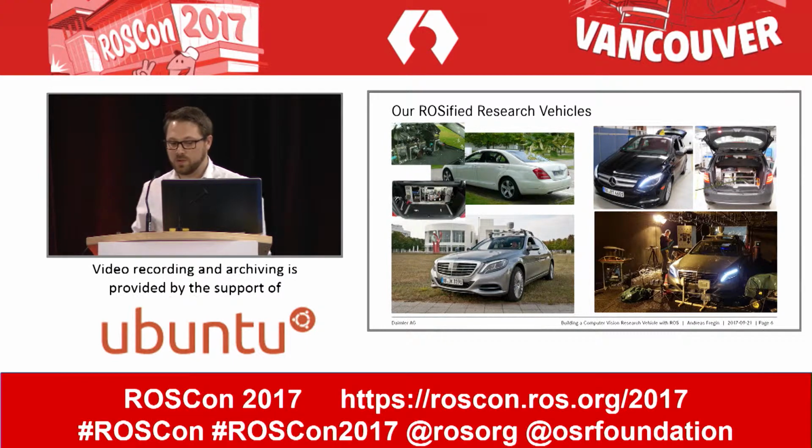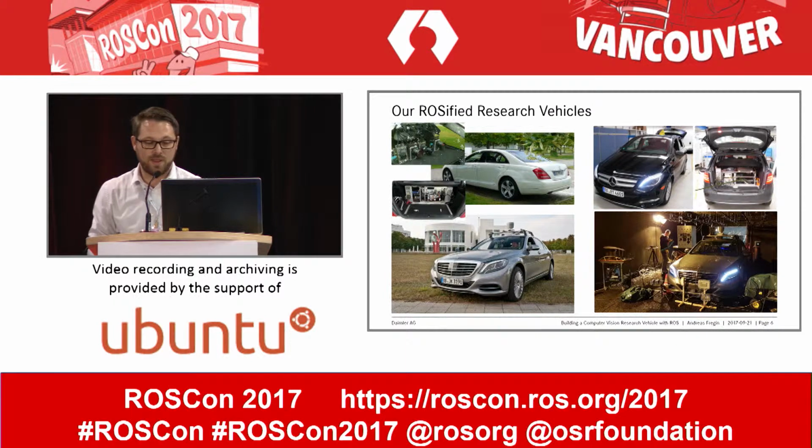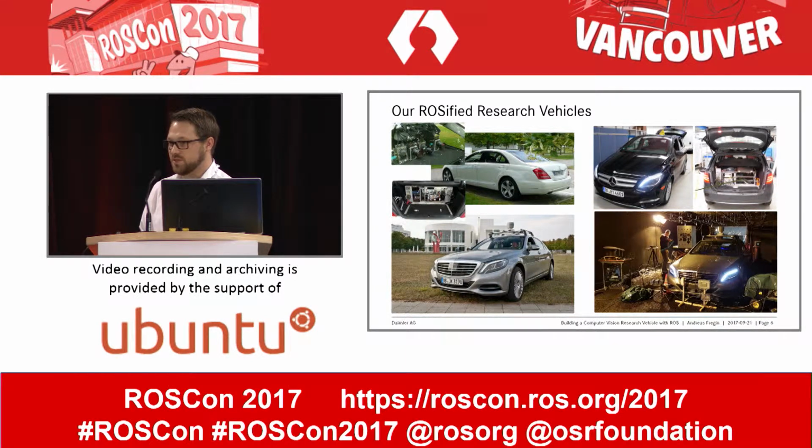Okay, as mentioned, our talk covers research vehicles, and here they are. Our team currently has three Mercedes-Benz S-Class vehicles, and another vehicle is a 2016 Mercedes-Benz B-Class Electric Drive used for another research project. The two at the top are used for traffic light research and have a relatively simple setup using the vehicle sensor data obtained from CAN buses as well as prototypically stereo cameras, and the other two have more complex setups including lidars, high-end odometry sensors, or infrared cameras. The one on the bottom left, for example, has 7 cameras as well as 3 lidar systems installed.